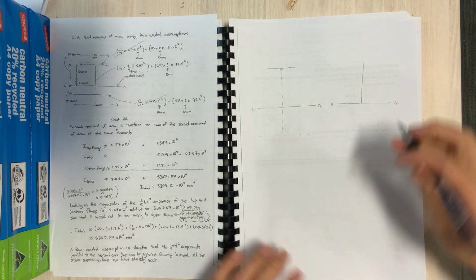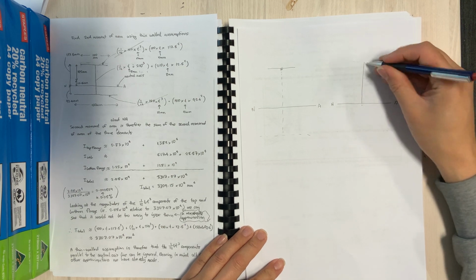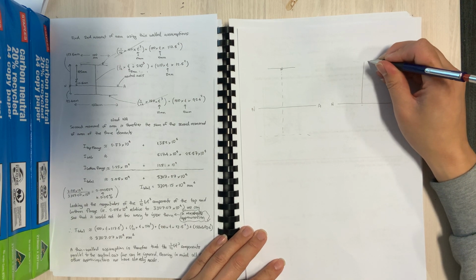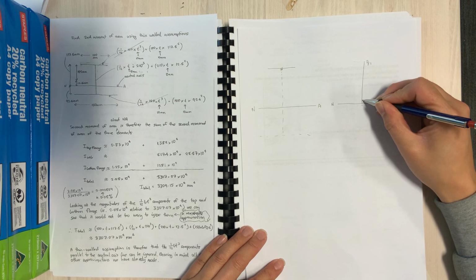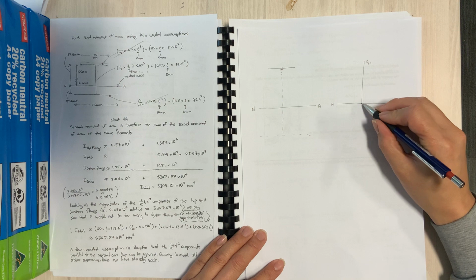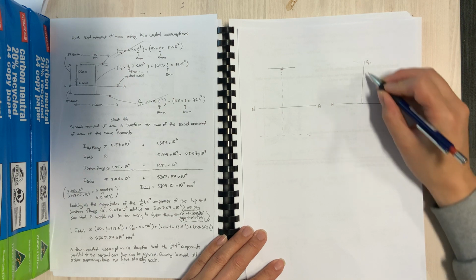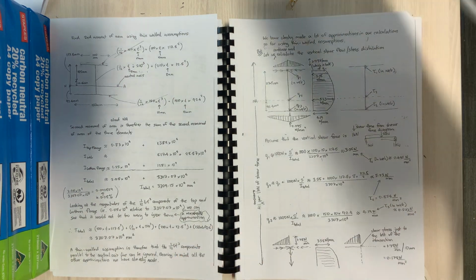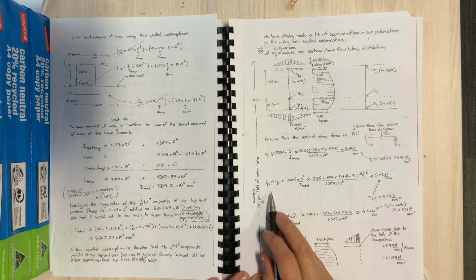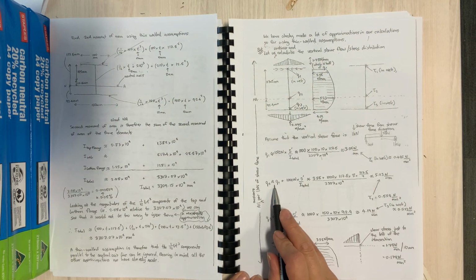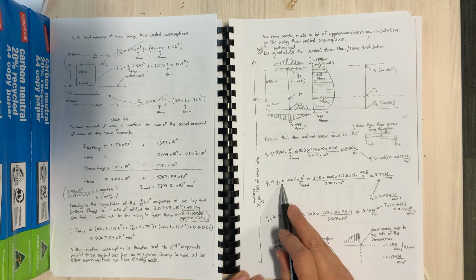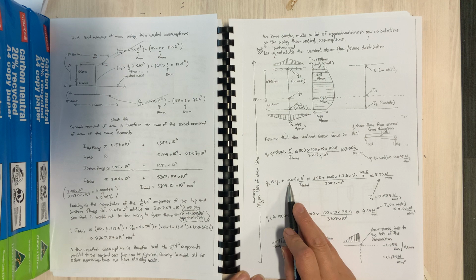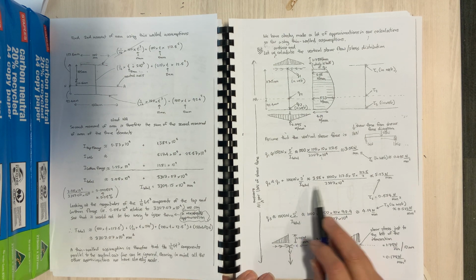So if we work out what this bit is, then we already know the value of Q1 at that point. And if we work out the first moment of area of that bit, then whatever the shear flow there is just Q1 plus the bit that we've added. So we can see that here. So at here, Q2, which is at the neutral axis, is equal to Q1, which we've calculated, plus the 1 kilonewton plus S dash over I total.